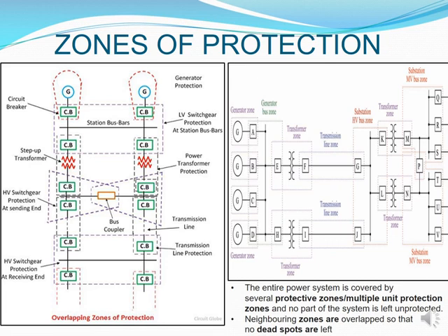The way that they have shown it is, if you look at the generator, each generator is linked with a circuit breaker, and they say that is a zone of protection. So that generator is being looked at by that one circuit breaker. And if the generator had a fault in it, then we expect that one circuit breaker to be able to act on that fault.